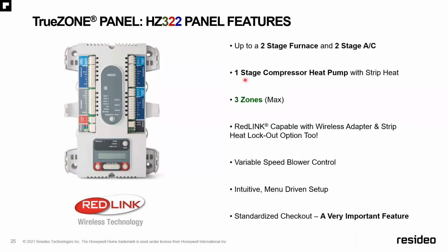But please remember, with heat pumps, 1 stage of compressor heat and the strip heat. If I had $1 for every time somebody tried to use this particular panel on a 3 heat, 2 cool heat pump, I'd feel like I'd won the lottery, okay?